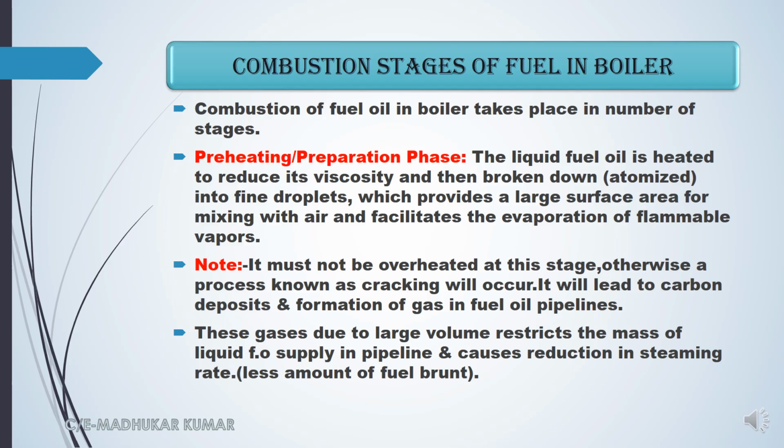Note, now we have to keep something in mind also. When we are doing the preheating, we should not overheat this, because overheating will cause a process which is called cracking. I hope you have heard earlier fuel cracking. So overheating should be avoided. Otherwise, it will lead to the formation of carbon deposits and the gases in fuel oil pipelines.